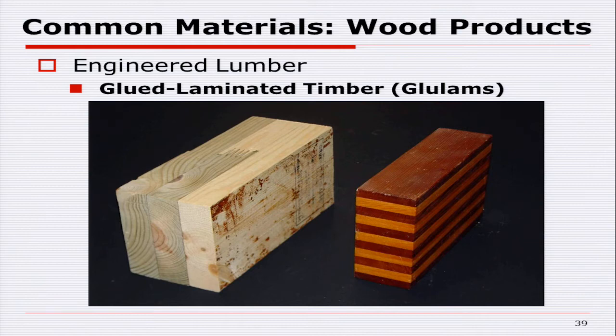So again, this is what's important. I talked about allowable design properties, right? Last time we talked about how if you have a wide distribution, that can be a problem because the wider the distribution, the farther the left tail area is way over here, and that's what dictates your design values. It's the weakest one that dictates your design value. You want a nice tight distribution of strength so that you're utilizing all your material really well.